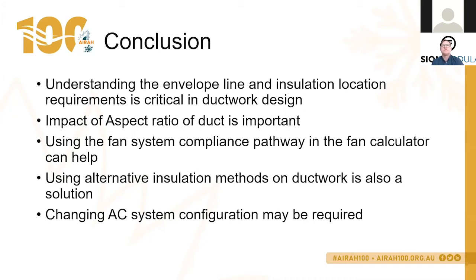You don't need to be defining the building envelope. That may be done by the sustainability consultant or the architect, but you do need to have an understanding. You do need to check it. You do need to possibly make suggestions back to the builder that it would be easier if the envelope line was in this location and not that location, and have an understanding of all of this so that you can optimise your ductwork design.